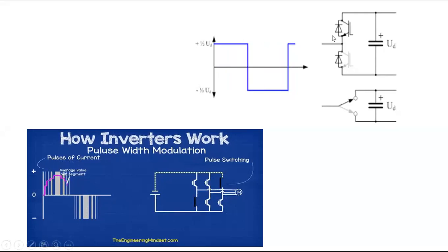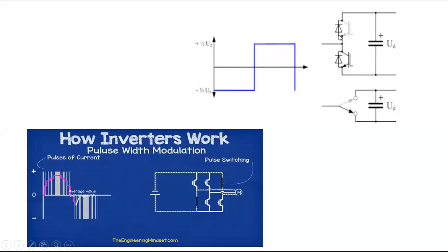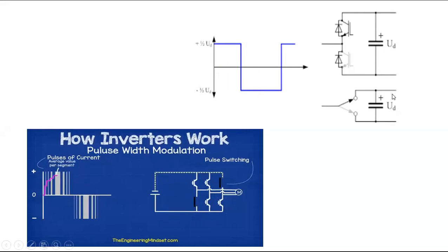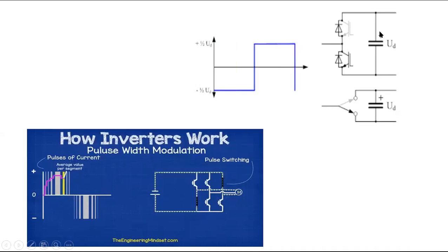Okay, so this is the example I am showing. First we are having a certain circuit where we are using the SCRs. You can see here BJT or any component. Input is DC supply. If the DC supply is not constant, we must place a capacitor in parallel with the DC supply. Capacitor provides constant voltage. So in any power electronic circuit, if in parallel with the supply voltage you are having the DC capacitor, the capacitor provides the constant voltage, even if the input supply is not constant.